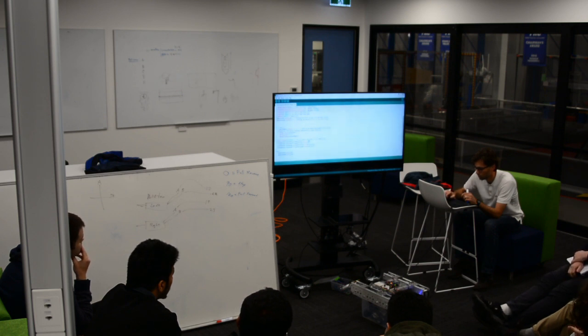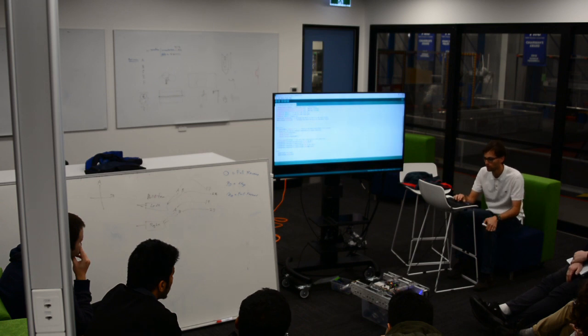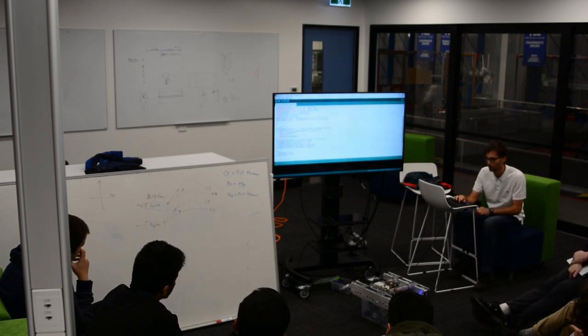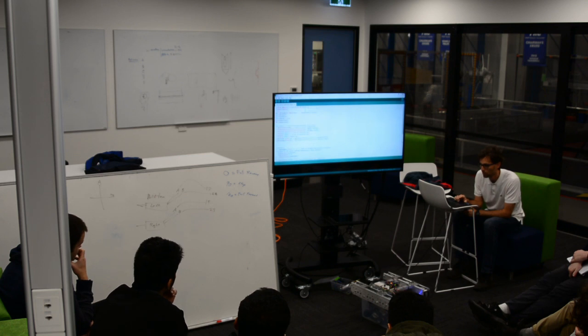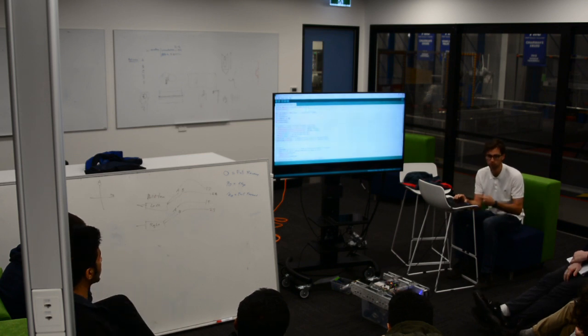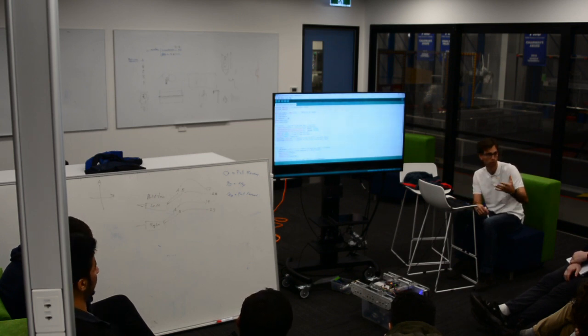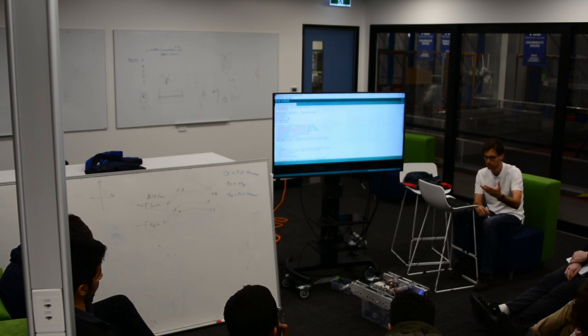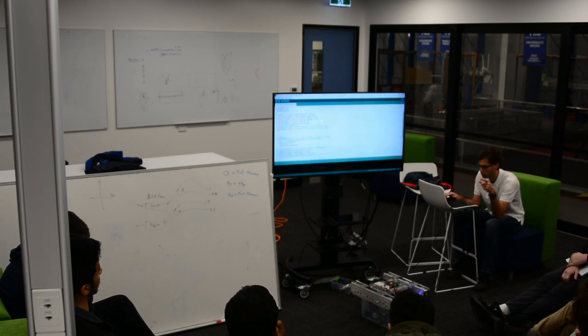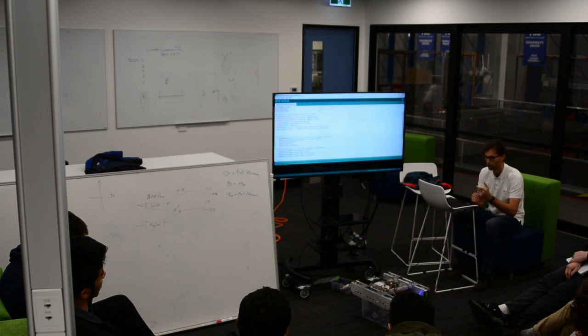We're gonna do something a little drastic here. This is how I started. 180 minus. Okay, so what it's gonna do is, our target position, so we've defined hopefully target position up here, so 1,000, so we're trying to get to 1,000. Every time we hit the reset, we're gonna try and get to 1,000. That target position is something that in software or control, you're gonna have to give it. That's gonna change. If you wanna move 10, then you give it a new target position. But for now, we've just said to go to 1,000.